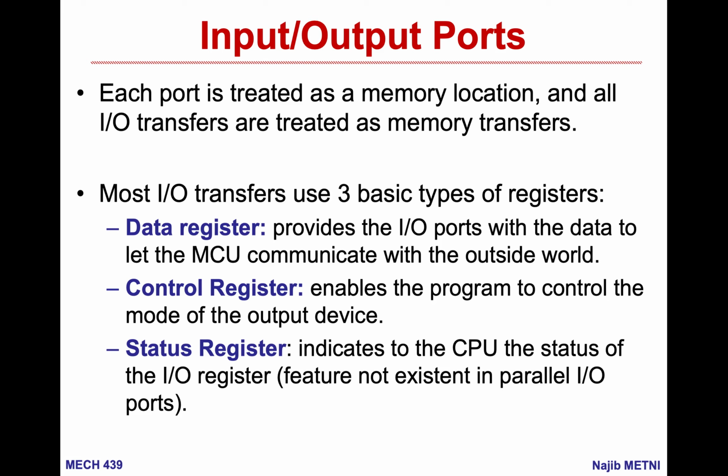So whenever I write a bit as one, this one will be output to the external world. So this is why we say that all input-output transfers are treated as just memory transfers for us. For us, it's just writing a 1 on a place, and because I know that this place is connected to a pin, the pin will output 5 volts.